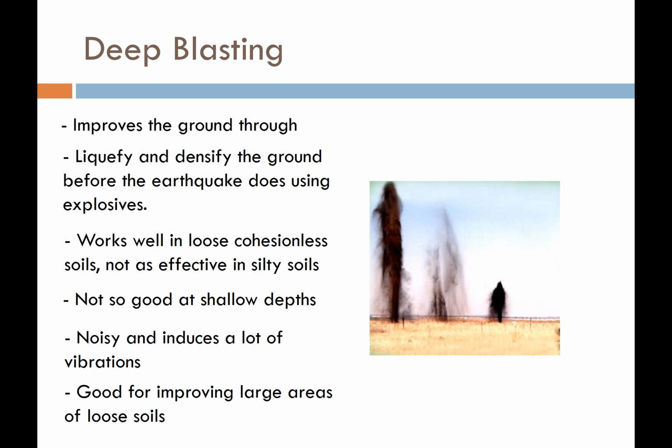Okay, another method that I haven't really seen used commonly, and probably because of permitting reasons, is deep blasting. So the idea is we're going to try to densify the ground at targeted layers by introducing pulse-like energy that's going to hopefully densify the ground, liquefy the ground. It blows water clean out of the ground when you do this. Because, I mean, we are purposefully trying to liquefy the soil in order to densify it. So think of it as pre-liquefying our site before the earthquake comes.